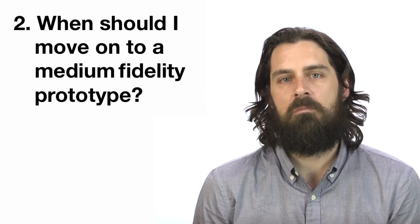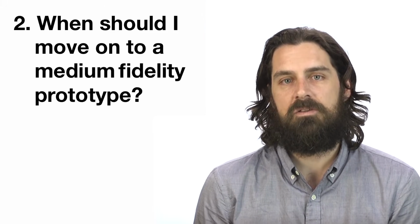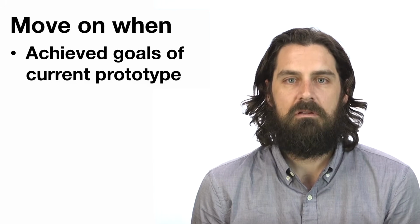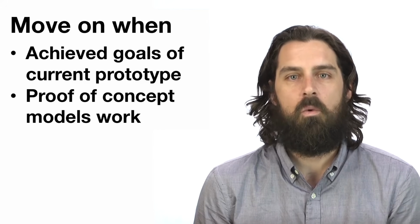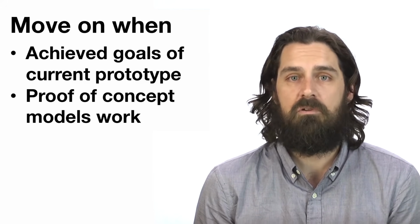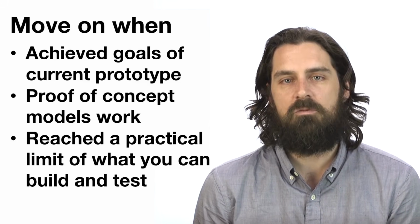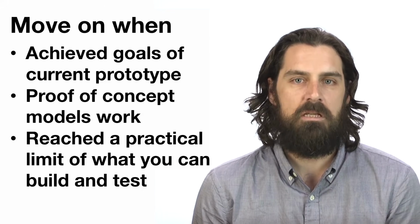Another big question teams will have is, when is it time to move on to a medium-fidelity prototype? Some of the answers might be when you've achieved the goals of your current prototype. Another reason might be if several proof of concept models work, you might be ready for a medium-fidelity prototype, or even an integrated prototype. When you've reached a practical limit of what you can build and test with a low-fidelity prototype, it really is time to move on to a medium-fidelity prototype.